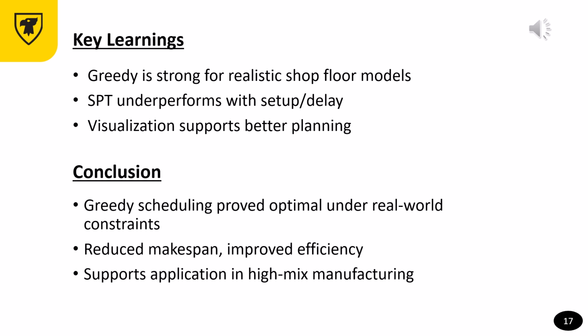Overall, we observed that practical scheduling must be tailored to account for shop-floor realities such as part transitions and operator shifts. To conclude, this project offered a practical perspective on scheduling challenges in an injection molding facility. We modeled a real-world system with precedence constraints, shift-based releases, and setup times. The greedy heuristic, although simple, turned out to be highly effective and outperformed classic techniques like SPT and EDD.